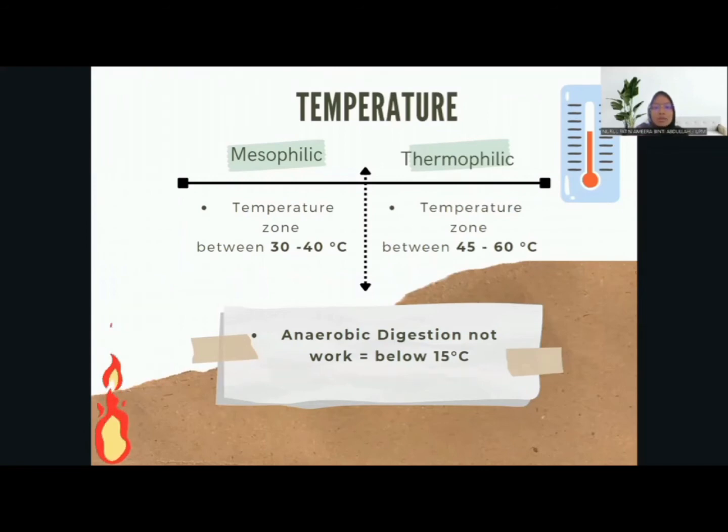However, underground construction or installation can buffer this temperature range. Mesophilic operation is more stable, can tolerate more change in conditions, and uses less energy. Mesophilic organisms, on the other hand, degrade more slowly, so you must give them more time. The system is more sensitive to alteration, although thermophilic organisms are faster.